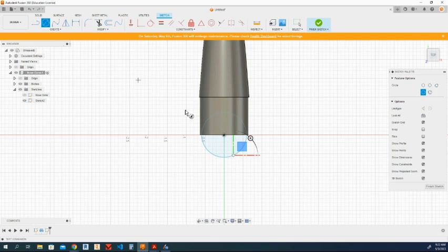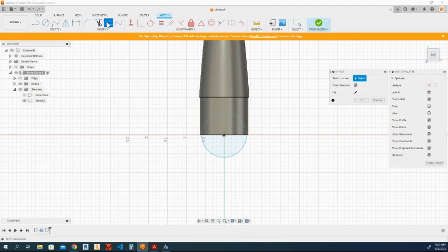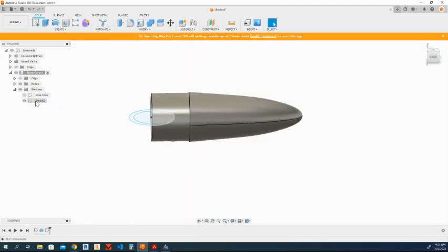Happy with that. Now I'm going to create an offset. So I create this offset tool. I'm going to select this. I'm going to move it in, and I'm going to make this 1/8 of an inch, which is negative 0.125. Gives me 1/8 of an inch. Finish that sketch. I'm going to name this thing my hook or loop. I like loop better. There we go.